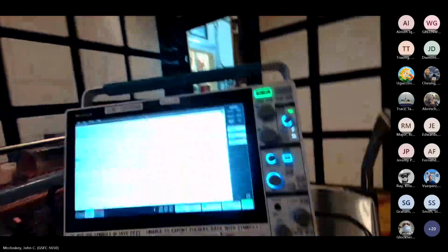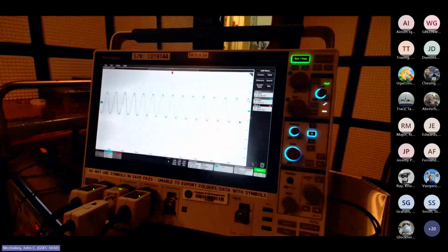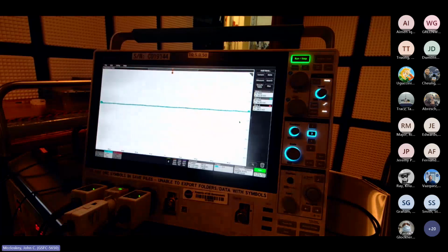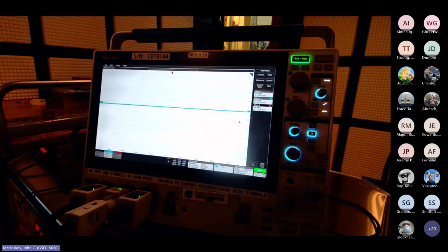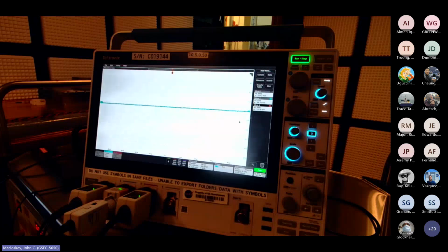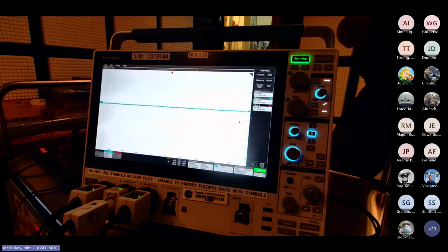All right. If there are no questions, we will go ahead and hook up to the unit under test. Let me turn off our drive signal. And so remember that one of the big guidelines when doing CS101 is you want your drive amplifier to be turned on and stabilized before you turn on the power to the equipment under test. That means turn on the drive amplifier, but also have your signal source connected to it.